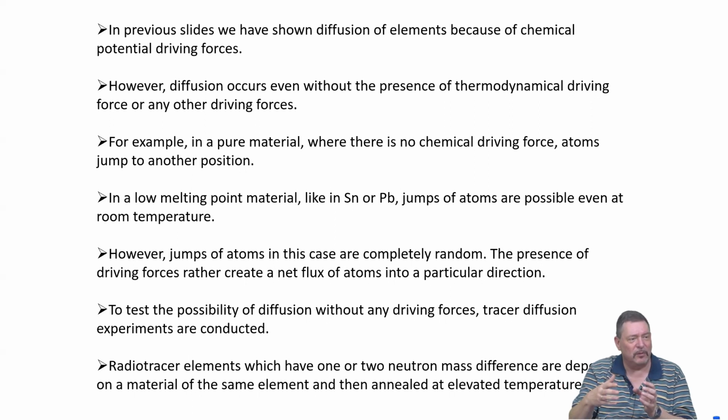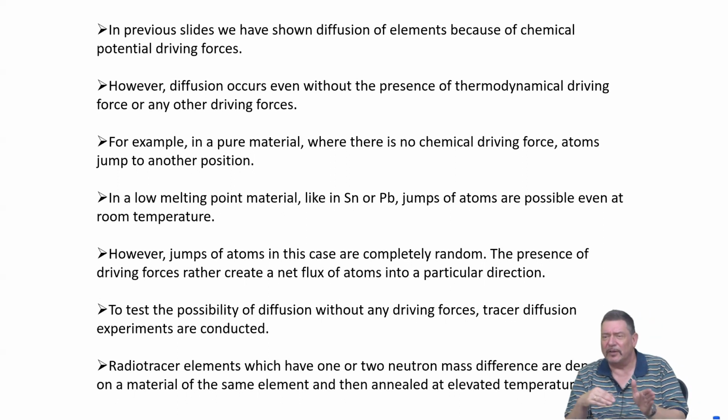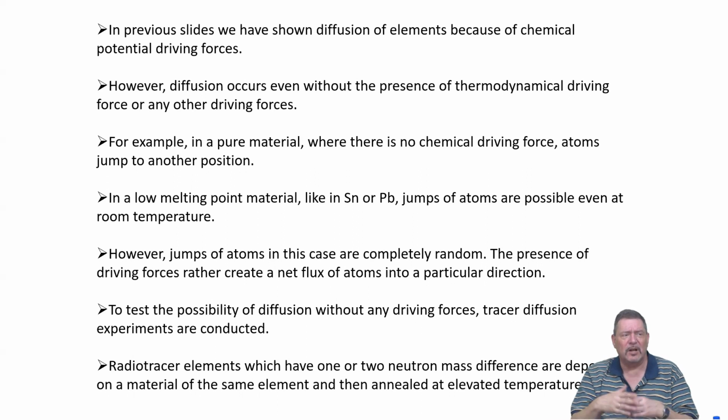And so we describe diffusion of like atoms, but still describe them in the framework of Fick's diffusion equations as if there were a concentration gradient. Right? So it's kind of balancing on a very thin wire. We have differences enough to be able to use this framework of equations, but they are not so large that it would disturb the system as a foreign atom would do. And this is the beauty of tracer diffusion, that you can really work on this thin wire, even experimentally, to get diffusivities of your system.